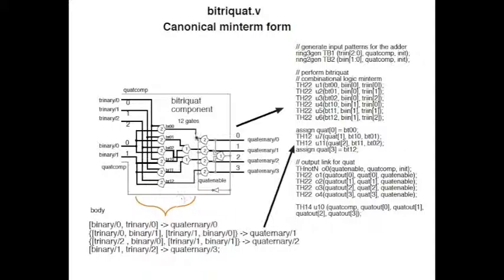Now this minterm circuit is identical to DIMS, delay insensitive minterm synthesis, which was developed 25 years ago by Sparso, Staunstrup, and Sorensen. And they developed it in terms of C elements and OR gates. Now, threshold 2 is identical to a C element, and threshold 1 is identical to an OR gate. But their difficulty was that in thinking of this in terms of C elements and OR gates, they couldn't optimize this structure, and this is not the optimal structure to implement the function with. But with NCL, we can optimize this structure.